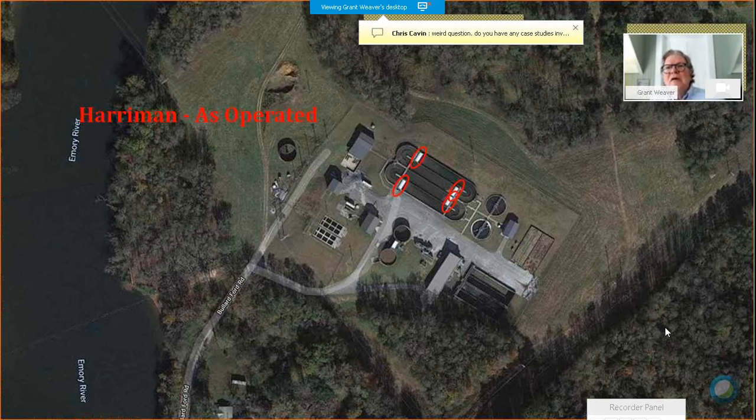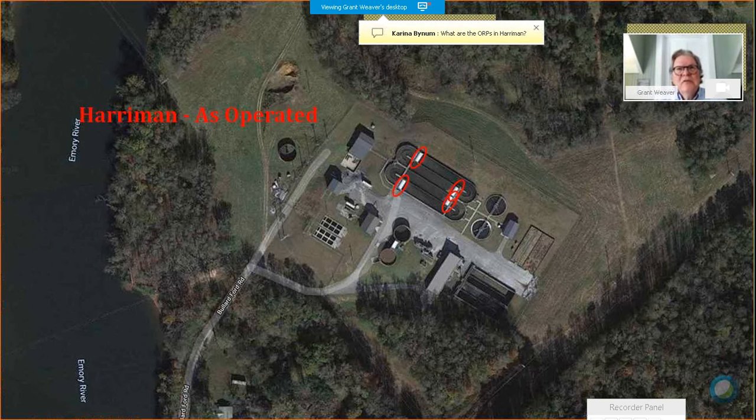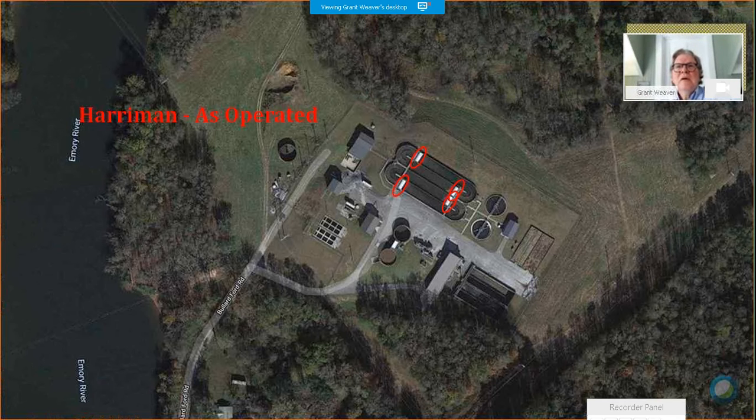So what our current thinking is, and in the last few months, we've made an effort to really boost the dissolved oxygen for a short time of day, in order to create a time of day every day with a really strong aerobic condition, thinking maybe we can drop, or he can drop, the phosphorus removal a bit more. So that's something that's ongoing, and we'll see what their success is.